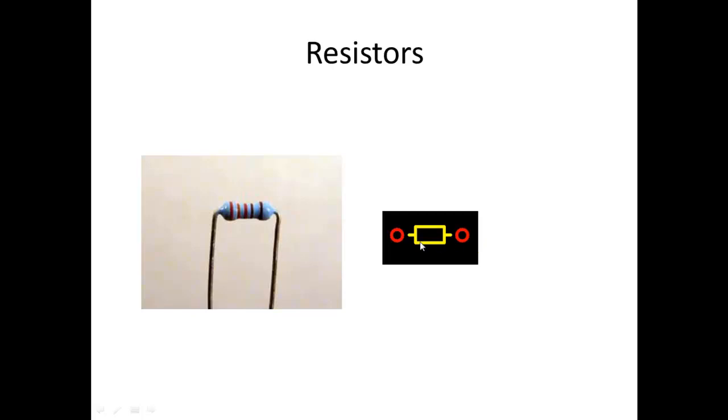So those two will be on the bottom side of the circuit board, and on the top side of the circuit board what we see here in yellow is the silk screen, which is printed in ink, and the purpose of that is to assist us in inserting the component from the top layer down into the holes so that we can place the component in the right orientation.